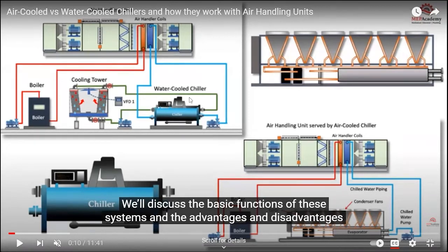So we're going to connect this heat pump, or this chiller. Here we have the water, so we go in this direction, we go up, and then we return this water and cool it down again in the chiller. But this is not enough with this kind of chiller, and we need a cooling tower. So we need another circuit, the green one, and we connect that chiller to the cooling tower. A cooling tower is good because it cools down water almost for free. We don't need energy to do this.